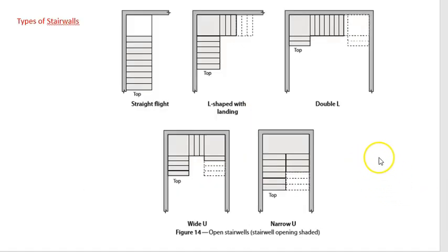They talk about a couple different types of stairwells. Again, in first year this isn't as relevant, but as you get into the later years in your apprenticeship, you'll have to figure out how to calculate the rise and run for each section in total for these different types of shapes of stairs. For the most part, in first year, we deal with the straight stair. So it's a single shot, just to introduce you to it.